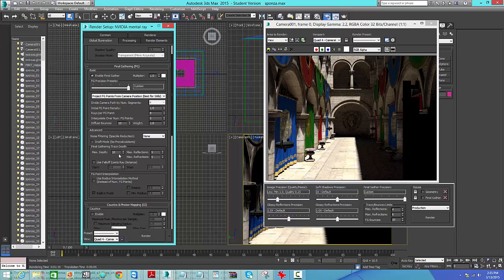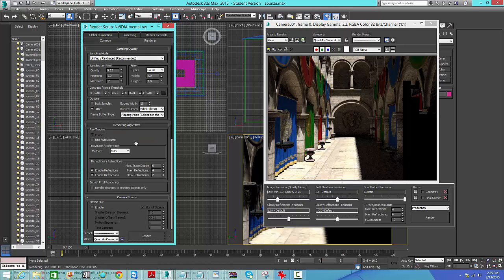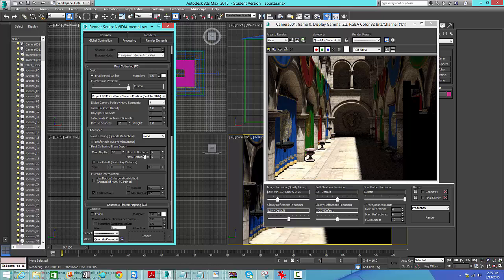And down here, there is another reflections and refractions and max depth setting for the final gather itself. That's similar to the one over here on this tab, where these reflections and refractions are for the ray tracer; the final gather has the same thing. And the diffuse bounces actually calculate into this. This is something that is in the documentation. It says that if you have these two set to 10 total, and then you have 10 diffuse bounces, when you actually render the file, it increases the max depth to the calculated max depth of these two numbers. So